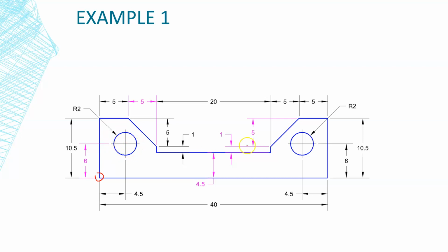So we're going to use a circle command, and the one that we're going to use is going to be the radius. Now also keep in mind that by default, when you use AutoCAD without actually going up to the circle command, so if I go C enter, by default it's looking for a radius. So we can choose to go up to the icon and select it, which I'll do on the first one. But for my second example, I'm just going to type in C enter, or I can actually use the enter button to repeat the last command. And since it's the exact same size circle, we don't have to put this value in twice. We can just hit enter to bypass that because AutoCAD does remember our last value.